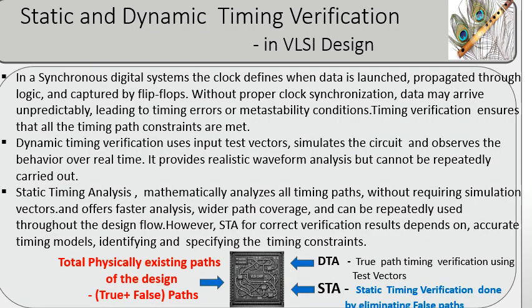In synchronous digital systems, the clock defines when data is launched, propagated through logic, and captured by flip-flops. Without proper clock synchronization, data may arrive unpredictably, leading to timing errors or metastability conditions. Timing verification ensures that all the timing path constraints are met.